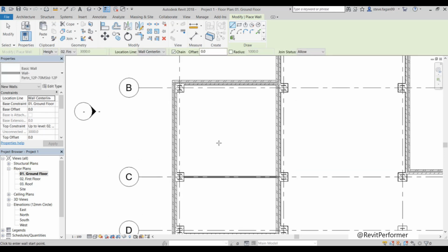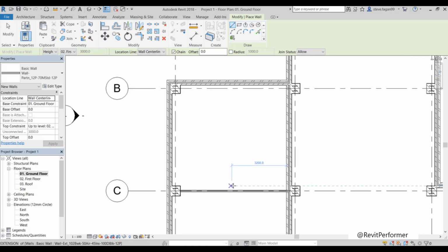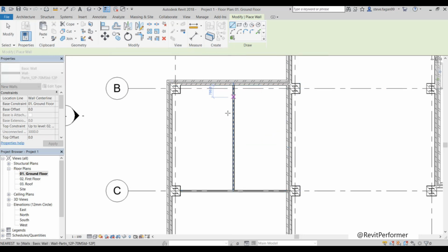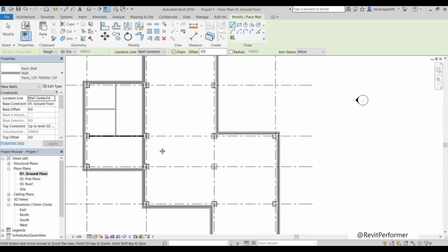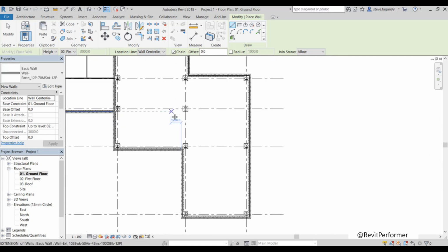As you can see in the PDF, all of those walls are equally spaced between each other. So what we can do is just hover over the edge of that wall and we'll get a triangle, which is our midpoint. And same again, once we get the triangle, it's the midpoint. So they're all equally spaced. We can go to the right-hand side.